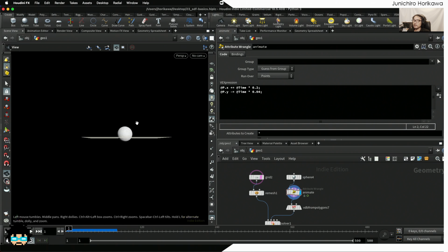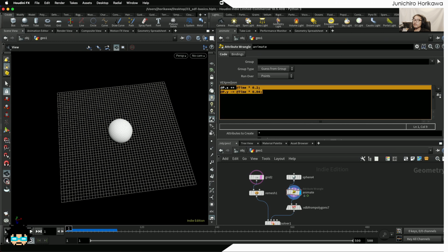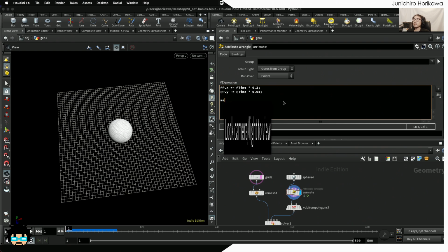Okay. Now, the next thing, I would like to rotate this sphere so that, combining all three transformations, you'll be able to have a more spiral movement. So let's first create an angle. Angle is equal to, say, time. And then use a matrix to rotate the point position. So starting with an ident, rotate matrix, angle, set 0, 1, 0.